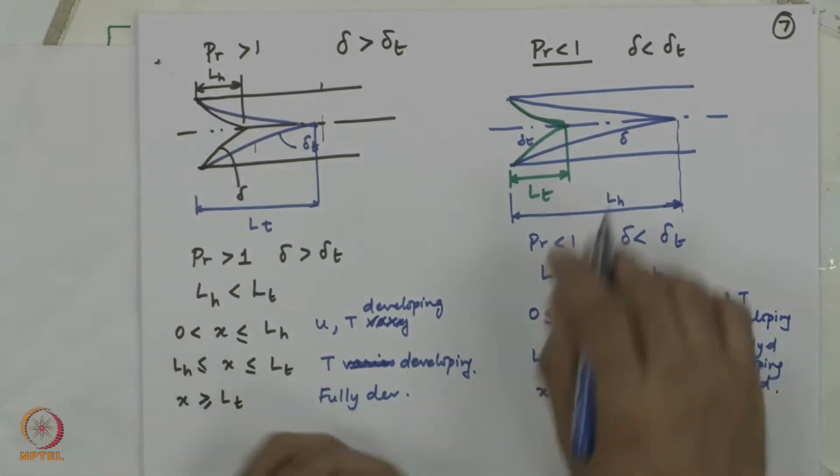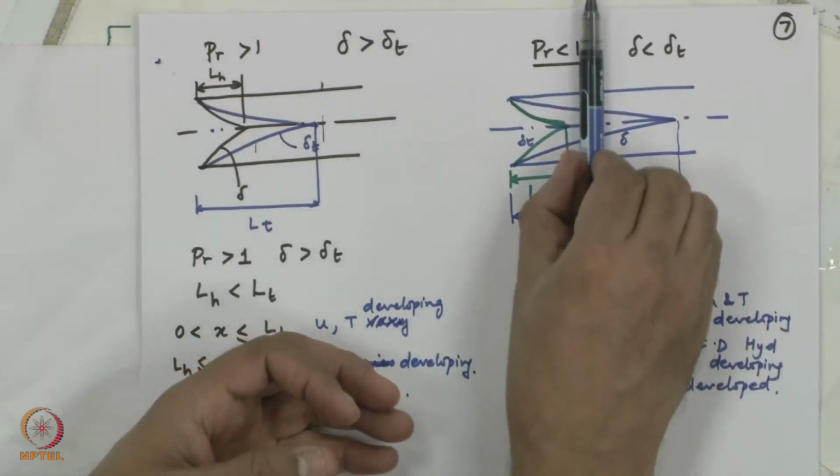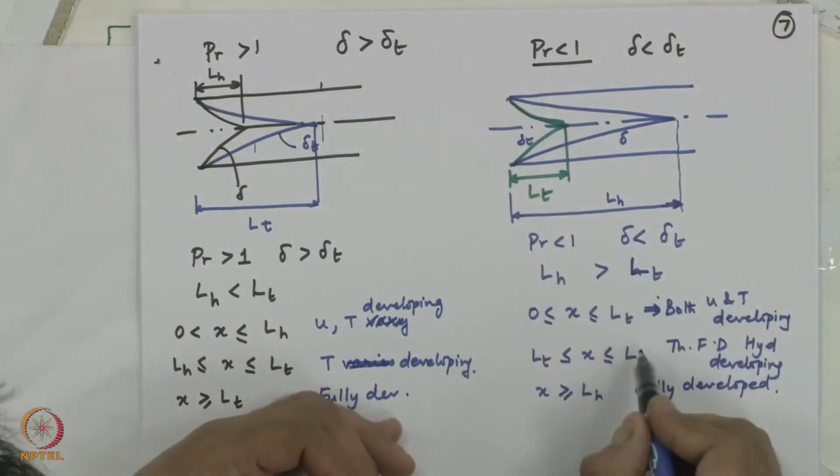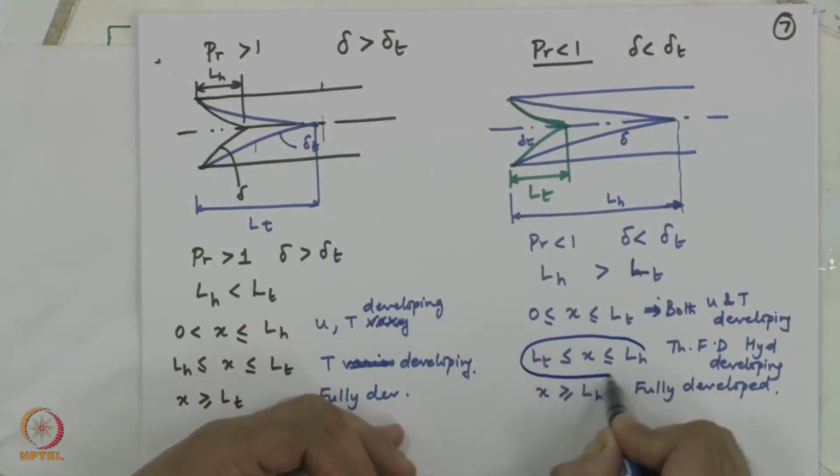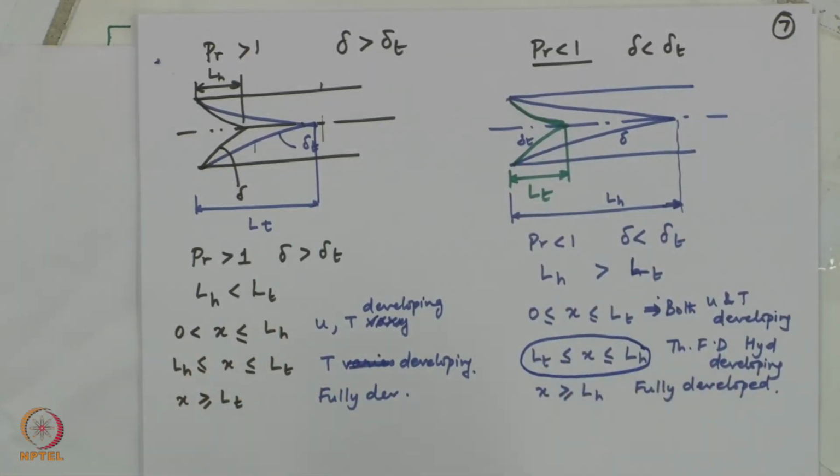Therefore, when I am in this part, in the middle part, in this region, my temperature profile has now reached the fixed shape. It is just going to expand like that. Velocity is of course changing with respect to x direction. When I am in this part, wherever du by dx is occurring in the equation, that will all go to 0. So, my equations become very, very simple, or simplified equations are there.